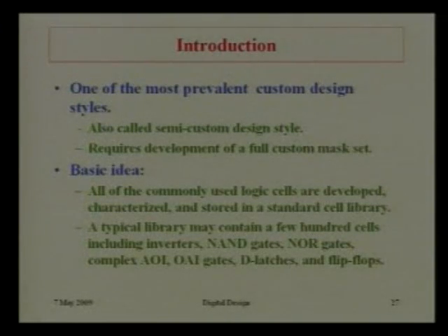But finally, if I want a chip, the AND gate I am using can be replaced by transistors. Finally the AND gate is synthesized by transistors, and the L by W of those transistors must be the same as in the fab lab that I will be using, because otherwise the L by W is different and everything will be different. Clear? So National Semiconductor has given that library here.